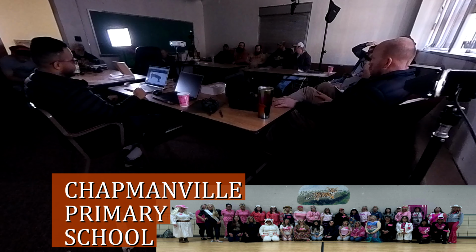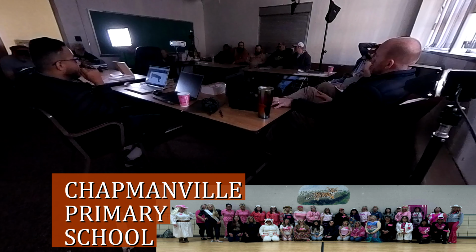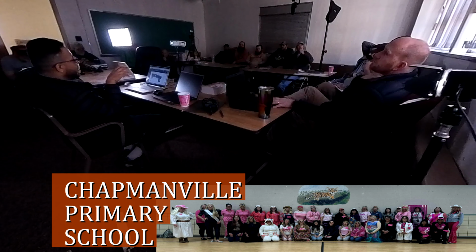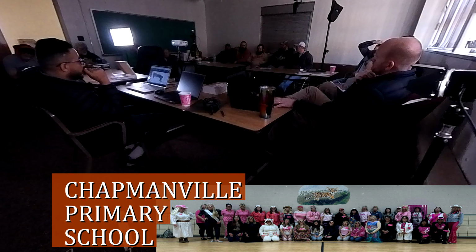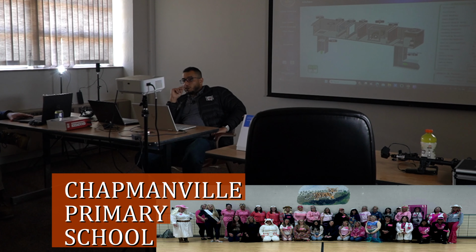So the Microtech controller isn't what your communication goes into. The Microtech goes into another controller and then jumps. Yeah. So it's like the Trane at home. There's two controllers. There's the unit controller and the controller you guys tap into. No, there's one controller. In Logan Middle, you've got BACnet cards, right? The only equipment that we have with a BACnet card is the AHUs and ACUs plus the chiller of Logan Middle. All the rest of the equipment, the whole.